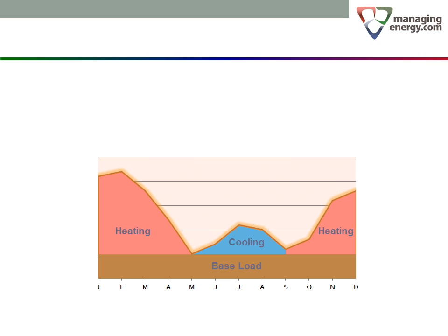So how are we going to reliably assess past energy performance? If we're going to figure out how well we did last year, we can't just compare against the year before. The effect of weather on the heating and cooling consumption is simply too strong. Of course, we could estimate the weather effect, but in the end, estimating always leaves questions and uncertainty. Estimation is not a good way to manage a major expense, especially when reliable software is available to handle the number crunching for us. The solution is to create mathematical models, or formulas, to describe how the metered consumption reacts to weather. When we have a model, we can plug the weather for any particular period into it to tell us how much we should have expected to consume.